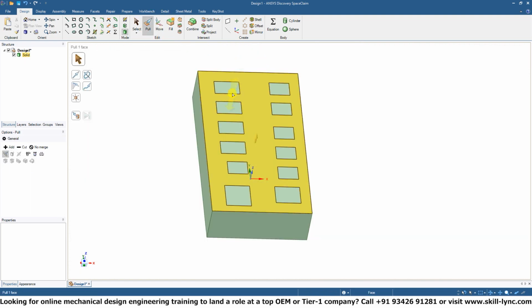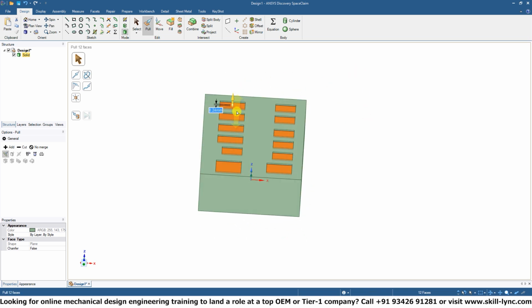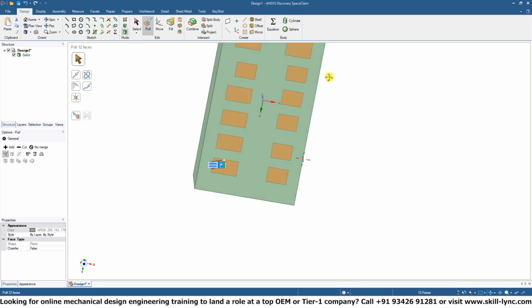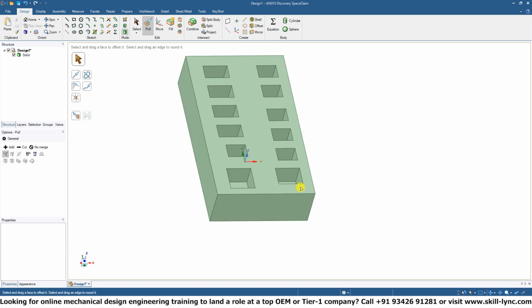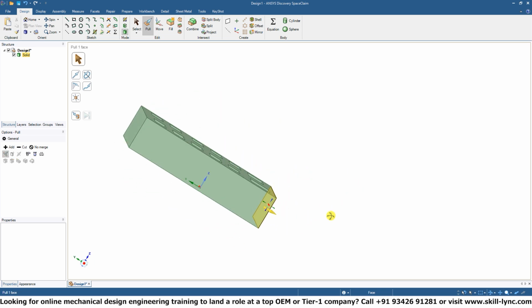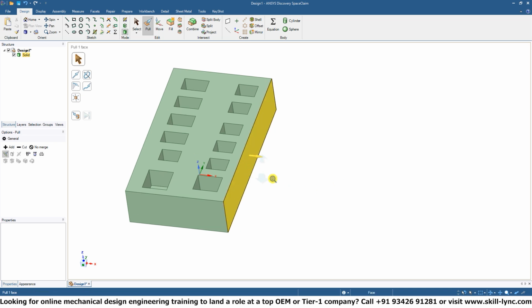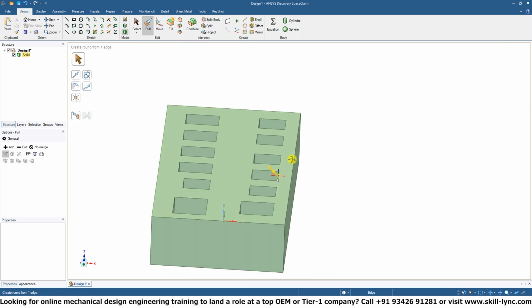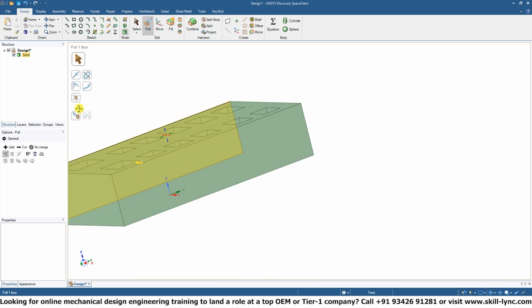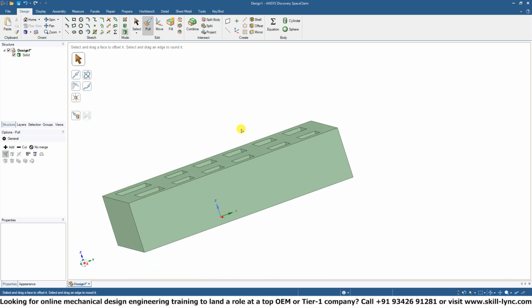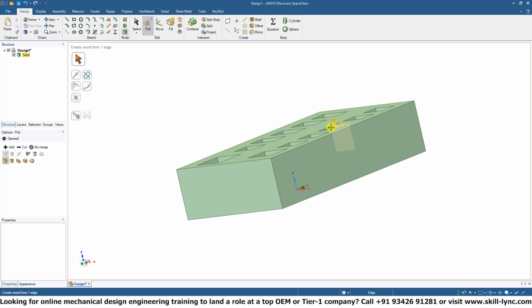If we hit pull right now, you can select all of these boxes that we have drawn, not the main body, by holding Control and clicking. Then if we do a pull cut, you can see what we obtained over here is similar to an ice cube tray, something that you could design a bit better with more accurate dimensioning of the parts and of the holes and more accurate placement of the holes to obtain the results that we wish.